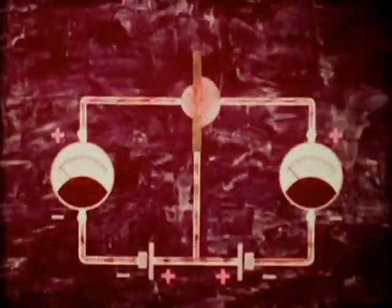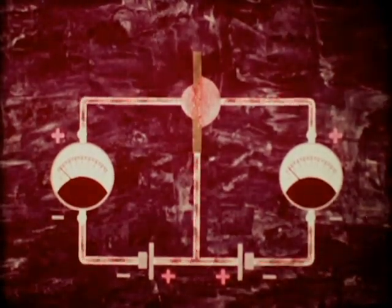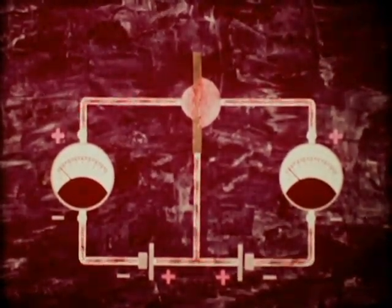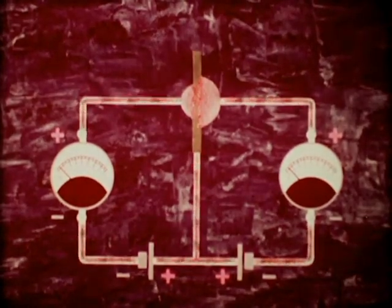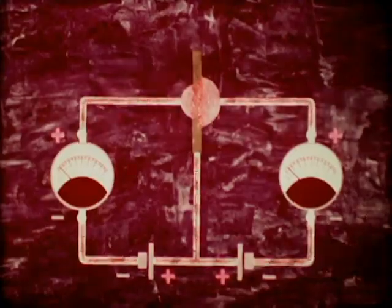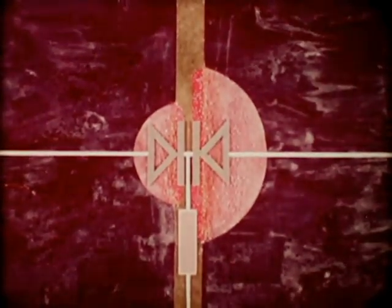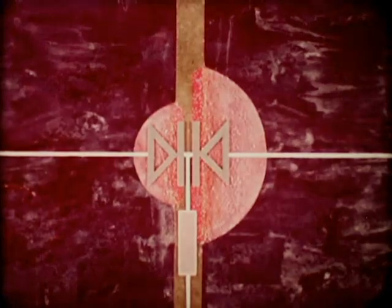The emitter and collector currents induced by the applied reverse voltages are very weak. This can also be seen from the equivalent circuit of the transistor, which comprises two reverse biased junctions and a base resistance. Under these conditions, the transistor is said to be operating in the cutoff state.